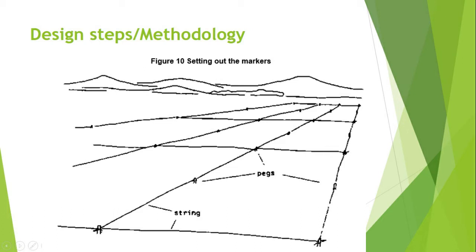Basins should be small if the slope of the land is high, the soil is highly permeable or sandy, the inflow stream is small in size, the required depth of irrigation is small, and the field preparation is done by hand or animal traction.